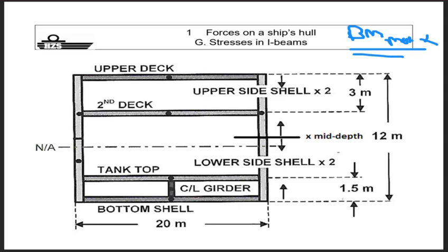You know, your stresses evolve like this. Up. You see your neutral axis, it is a bit lower than mid-height. Realistic for a vessel because you have more material in your bottom than in your upper deck. What is your stress level? This is your stress level. How do you come up to that stress level?